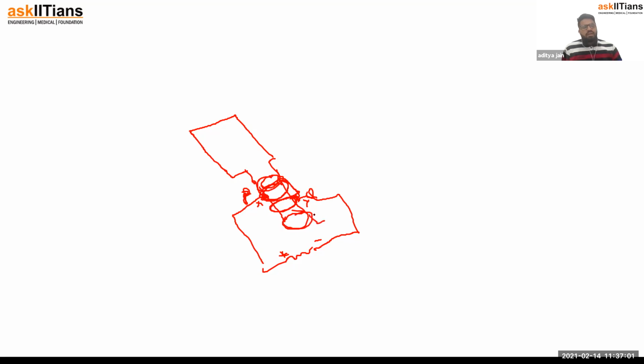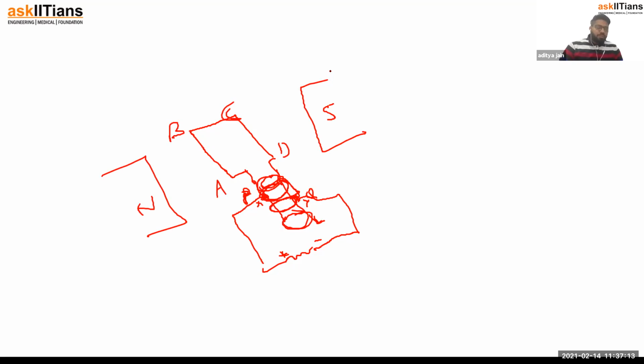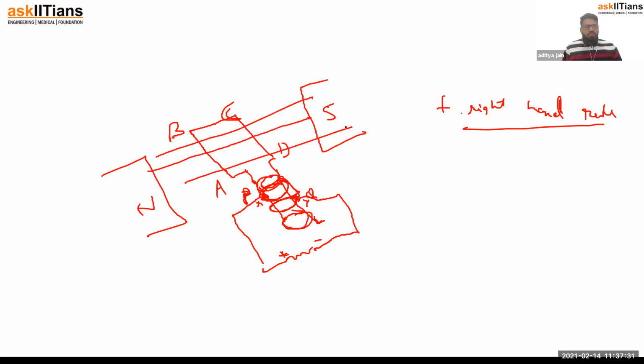With the help of the shaft, this is the axle. If you rotate this axle by any mechanical means, then the coil ABCD will rotate. So see what will happen. This is the magnetic field present. You know the rule which we use to find the direction of induced current, that is known as Fleming's right-hand rule. We will use Fleming's right-hand rule to decide the direction of induced current in the coil. Clear? Now, the direction of the magnetic field is from north to south. Suppose I am rotating this coil ABCD in the clockwise sense, which means AB is moving upward initially.